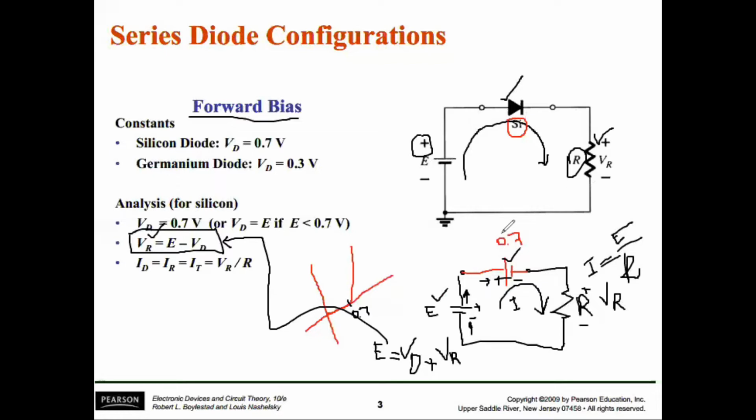Similarly, if we have more than one diode here, let's say we have another diode here, and we want to analyze it again. What will we do? We will just model it. If this is, let's say, silicon again, and not the ideal condition, we will again model another voltage source, and then the resistor.